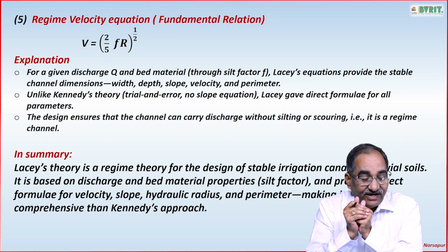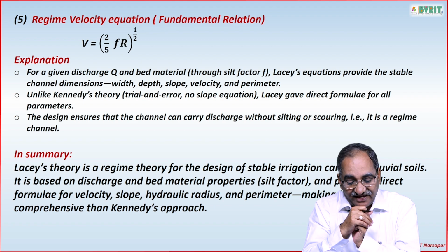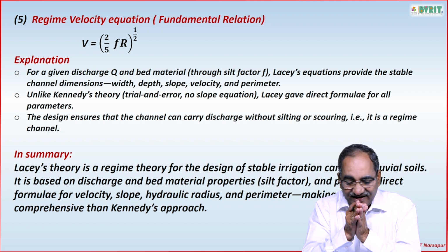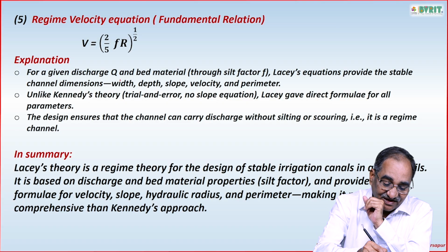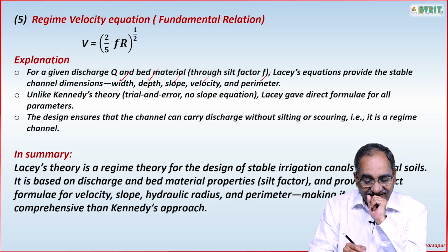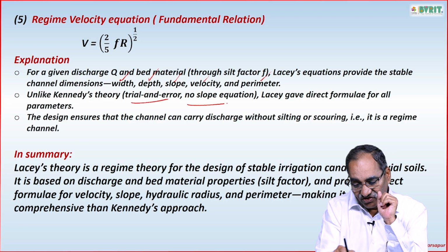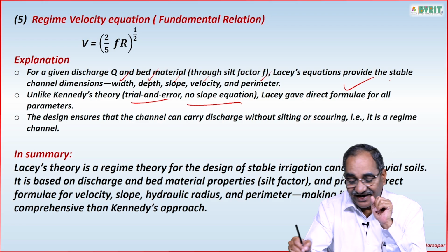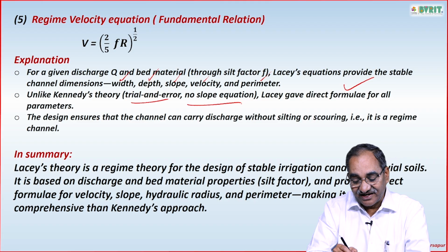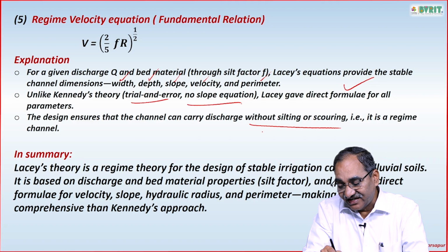Explanation. For a given discharge Q and bed material, that is through silt factor, Lacey's equations provide the stable channel dimensions: depth, slope, velocity and perimeter. Unlike Kennedy's theory, which is trial and error, where there is no slope equation, Lacey gave direct formulae for all the parameters. The design ensures that the channel can carry discharge without silting and scouring.